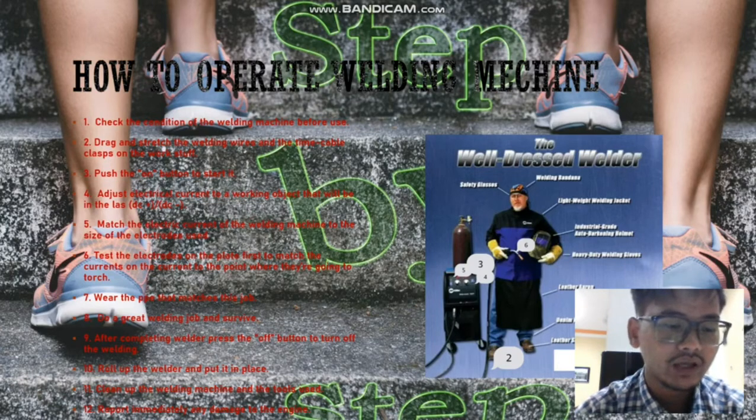Five, match the electric current of the welding machine to the size of the electrodes used. Six, test the electrodes on the plate first to match the current to the point where you are going to weld. Seven, wear the PPE that matches this job. Eight, do the welding job carefully and safely.